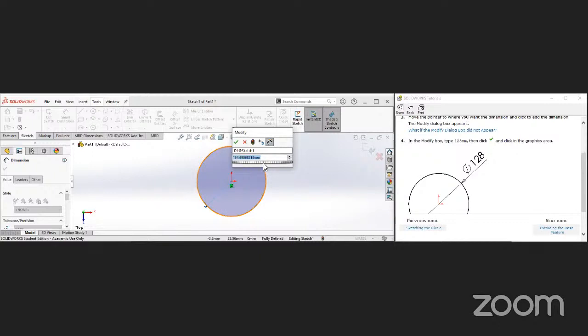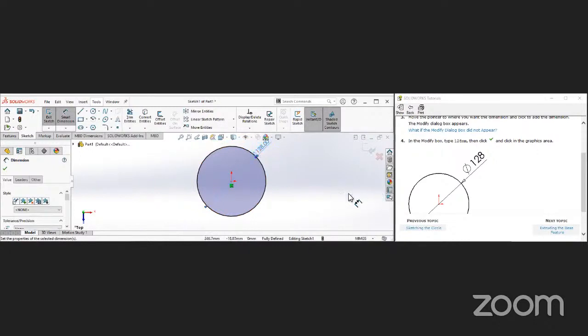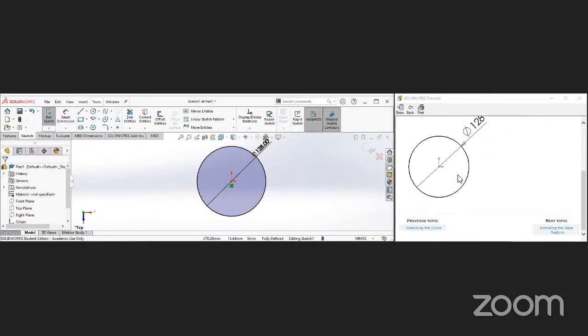We picked just an arbitrary size, but now we can come back in. You can see this dialog popped up where we can tune exactly what we want. It said we want 128 millimeters. So we click that and the circle resizes to 128. If you notice, before it was blue, now it's turned black. Black lines means that sketch is fully defined. So I could click on this, I could try and drag it around and it wouldn't change, whereas before I could grab the radius of that circle and make it bigger or smaller. But it's great because it's fully defined now. That's exactly what we want. Now over here, there's often a checkbox for the dimension. We can click that. That dimension is locked in.